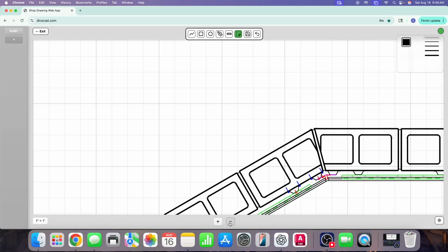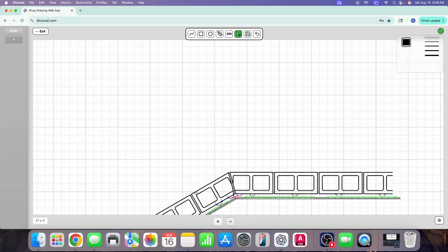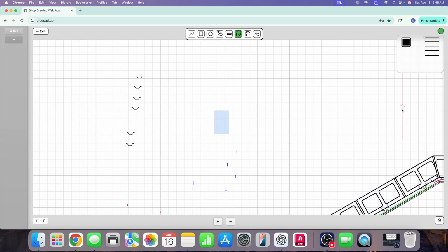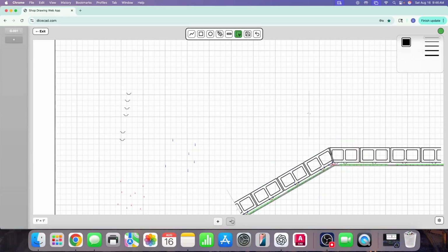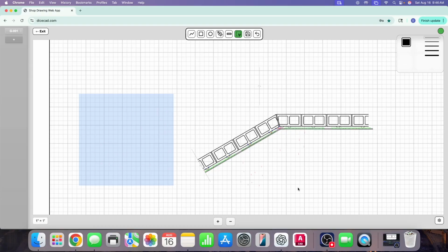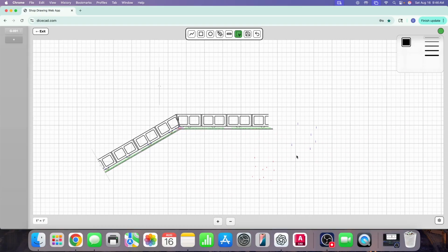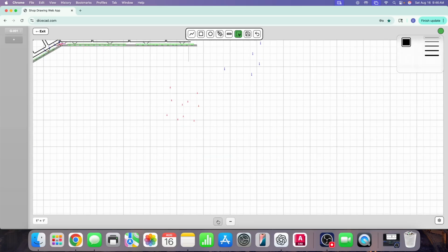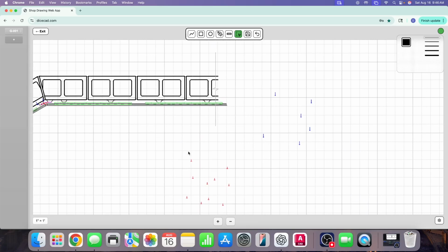All right, so the next thing is, let me just do this now. Actually, first of all, I don't need any more of these hat channels. All of these screws, I can move them to this side. I'm gonna move this in here where I'm gonna cut it. Move my screw, I need 2 in here, and then 1 on each hat channel, holding the clips to the wall.